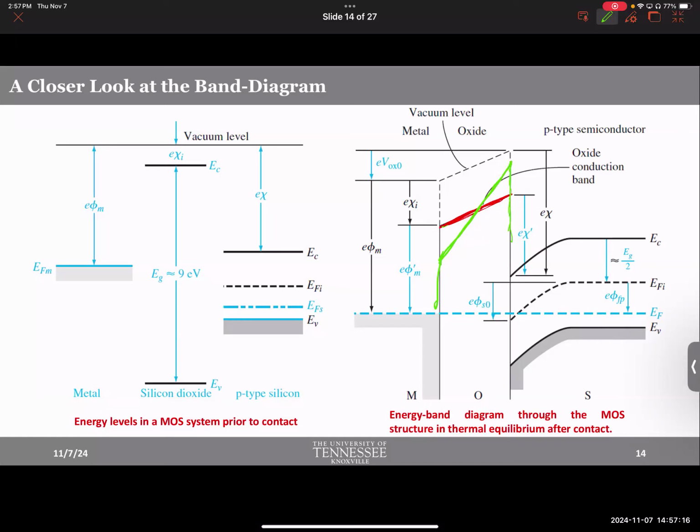Do you like to drop voltage across the oxide? Is that why you are making the device, so that you will drop voltage across the oxide? No, this is basically a loss, right? You have to use oxide. Sure, you have to live with it, but then it drops some voltage. So the less drop you have, the better it is.